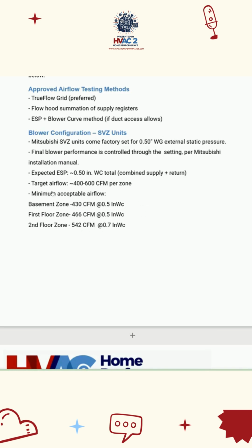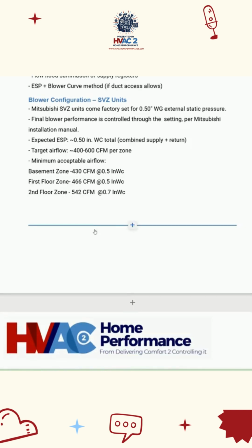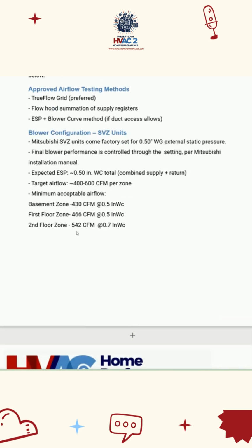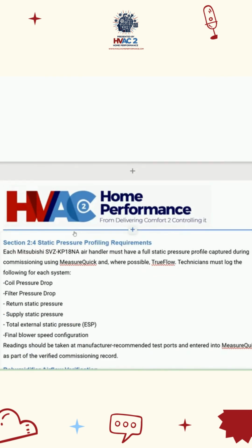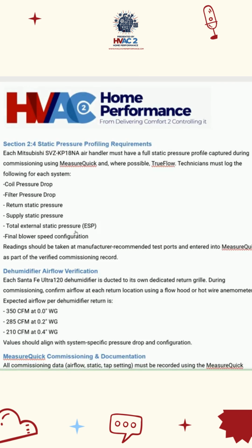Another thing is, these things can put out 21,000 BTUs of heat, okay? They're 18,000 BTU pieces of equipment. If they need to put out max heat, they need max airflow. So you have to facilitate that airflow. So these ducts have to be designed to facilitate max airflow, even though the system probably will not always operate that way. It'll usually operate at something much less. But remember, better to oversize them than undersize them. All right, when it comes to ductwork, not systems, ductwork.